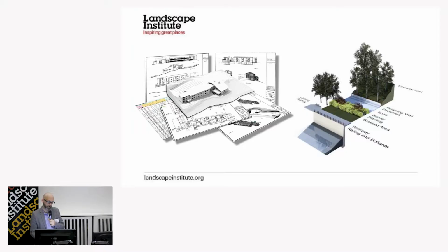From a BIM point of view, on the left-hand side here, you can see maybe a typical representation of what a BIM project would be. So we've got both the site and the three-dimensional model. And again, just to emphasize the point, the difference between that and a simple visual model is that you can, one, start to take sections and elevations that are live from that model, represented by the documents that you can see here, but also embedded in that model is data, and from that data you can create live reports that are associated to the model. So they are not separate silo entities.